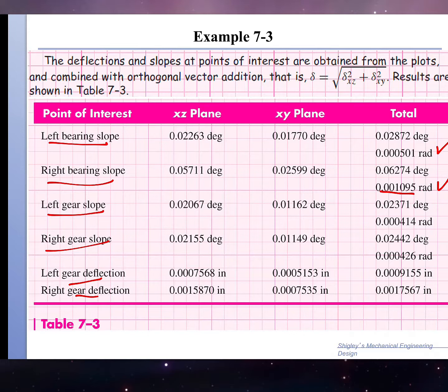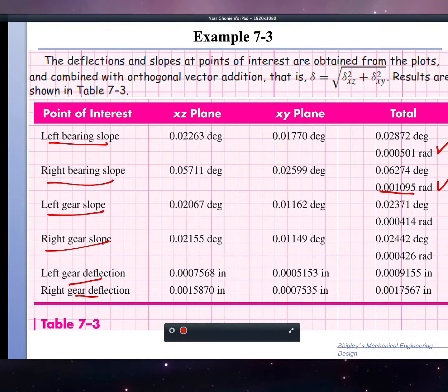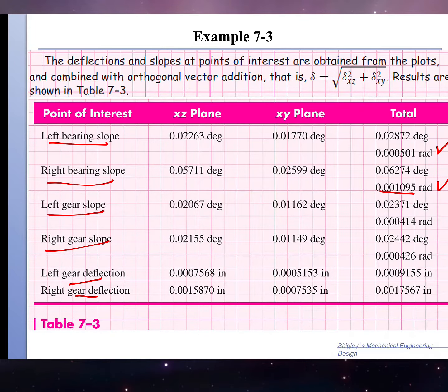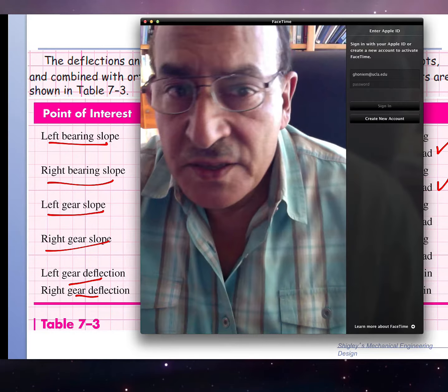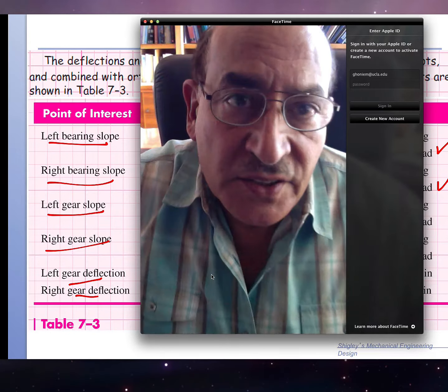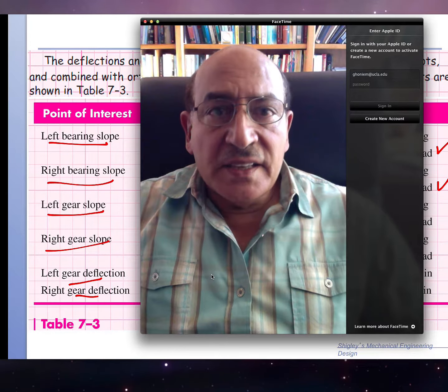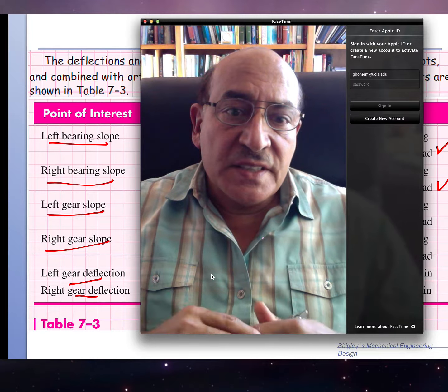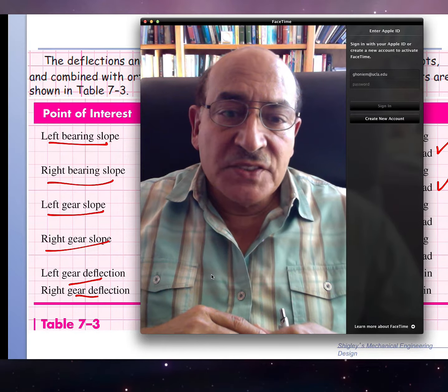So you now have a problem in the deflection that you have to correct for. So the actual practical question is, do we now reconsider redoing the calculations again and changing all of the diameters and then find the corresponding deflections?